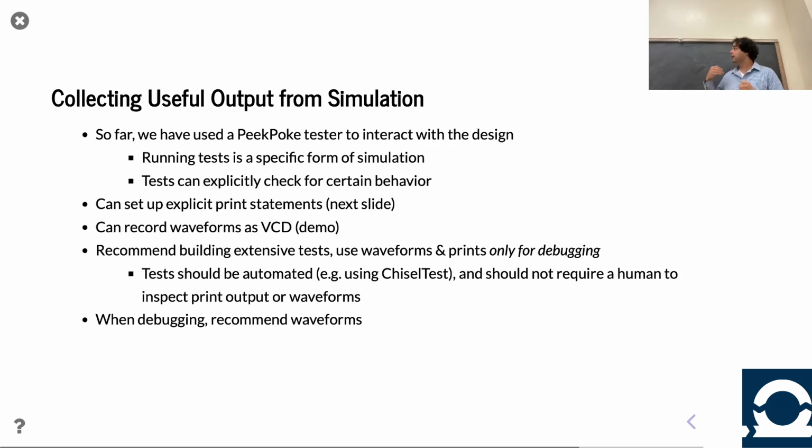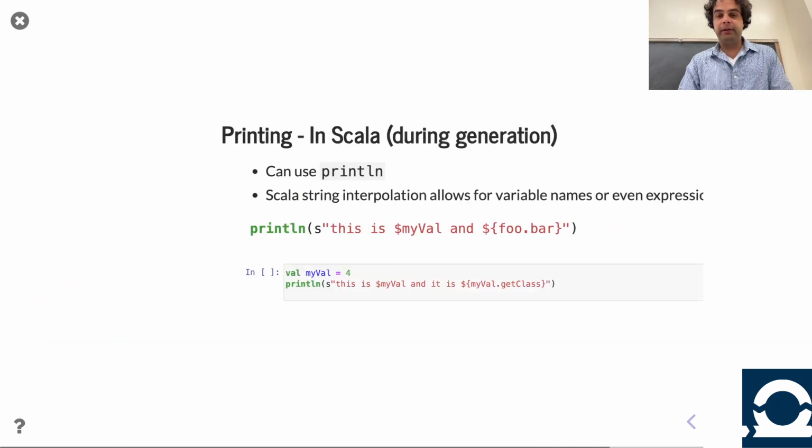A test case is both an input and expected output. And you want to put that intelligence, that insight, into a unit test, right? So in this case, a Chisel test. And so your Chisel test is going to check what's correct, right? So it's going to be those inputs and then the expected outputs, and making sure they match up. The stuff with prints and waveforms, that's only for debugging, right? It's only making sure things check out. So let's see these two things in practice.